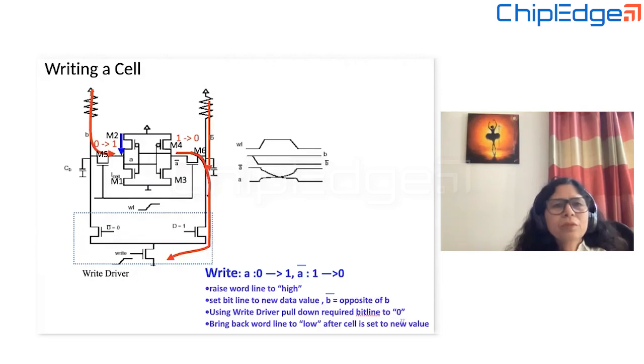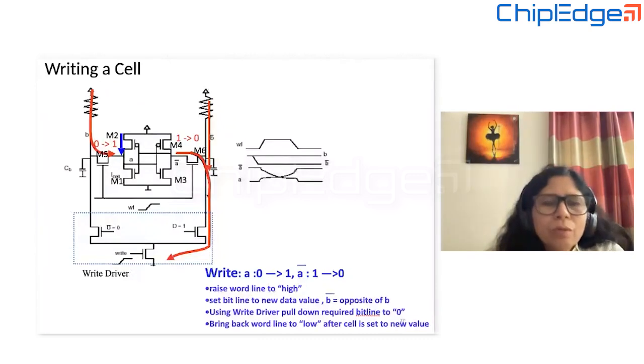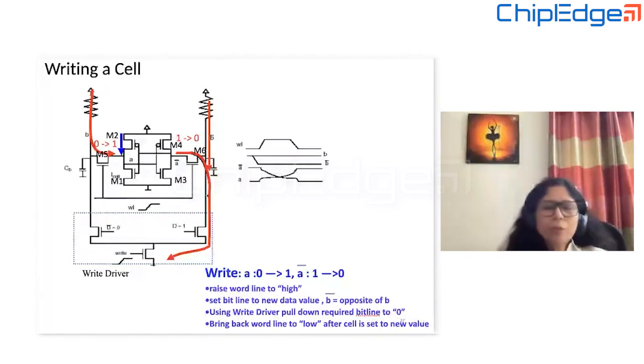In most of the papers they say 6T SRAM is not stable for read and write operation, and many other circuits are designed for lower nodes. In my experience, even till 3 nanometer, the SRAM cell being used is 6T. When we talk about 7T, 8T, those SRAM cells are used when we want to increase the number of ports.